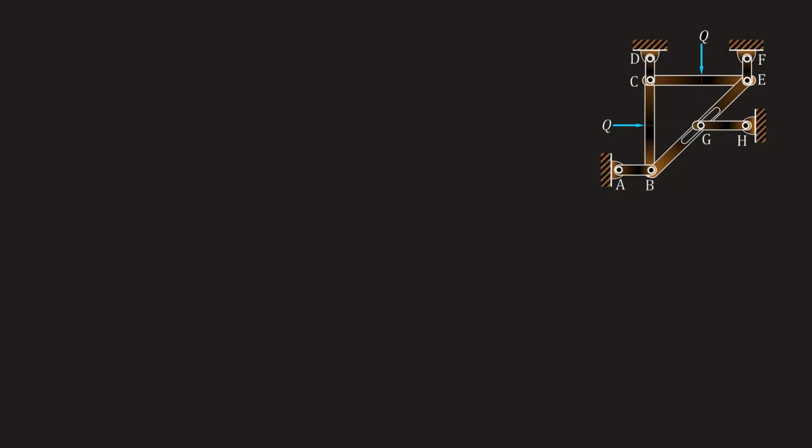Let's find out. Now, this given structure has load acting at locations other than the joints, and therefore this is not a truss but a frame. In this frame, when Q acts on member CE, there will be load at joint C, which will be distributed to the members CD and CB, as well as at joint E, which will be distributed to EF and EB or BE.